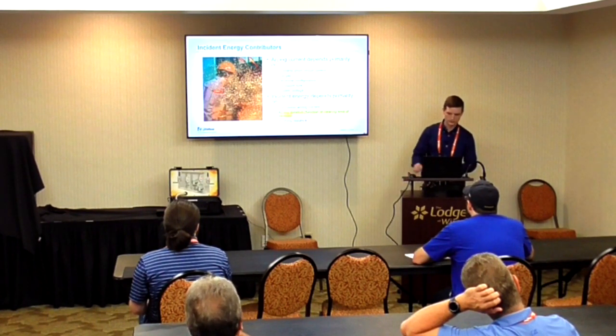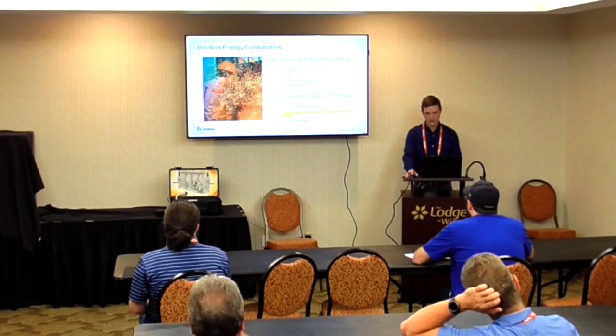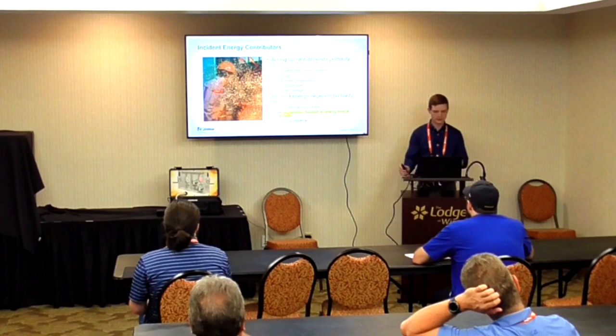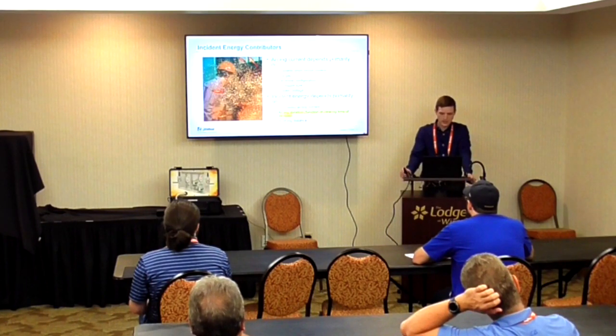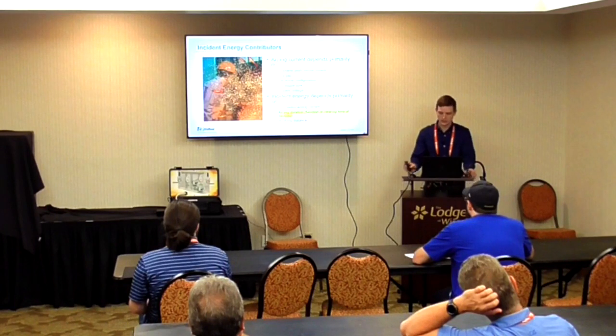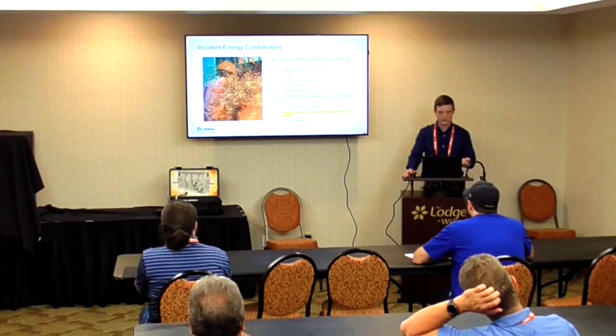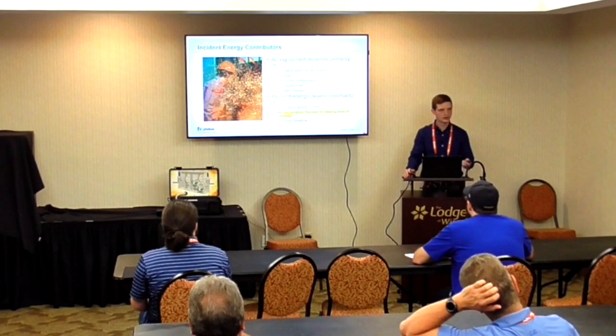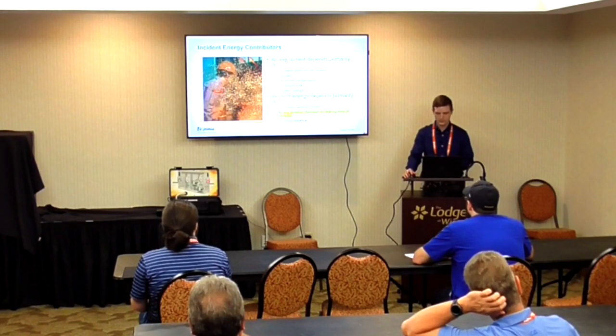Now, just to cover some of these in a little bit more detail, the bus gap for 1584 did have some updates in the 2018 revision. They now have default values for 208 volt to 600 volts and 600 volts to 15 kV, so they do have spacing guidance and other guidance in there for that. And the electrode configurations were also updated in 1584. We're going to take a closer look at those later on.